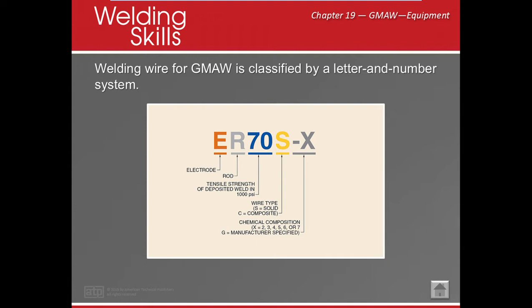Now, imagine on the inside is a bunch of little boxes. These little boxes represent all the different rods and electrodes that are used for GMAW. Each box is a classification. For example, ER70S-2. It must meet those standards of the specification and specifically the classification. So this is a classification.